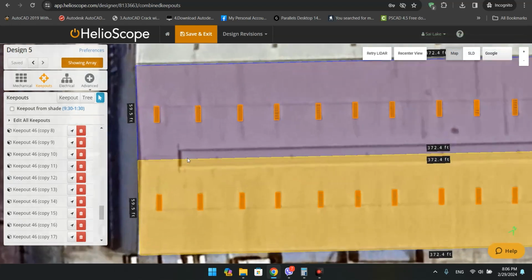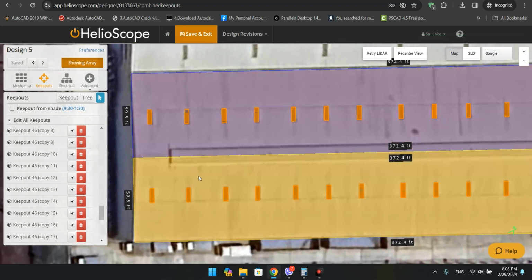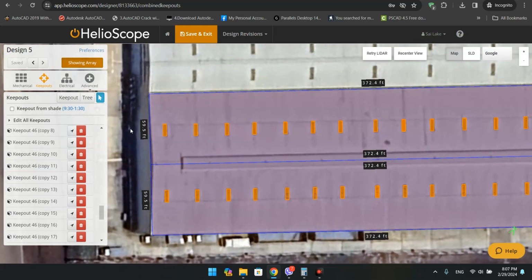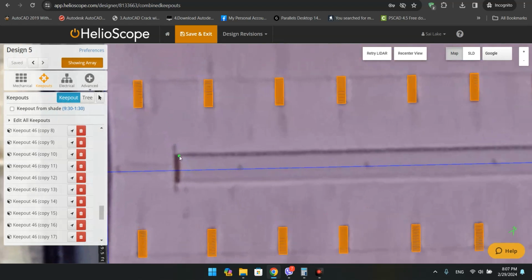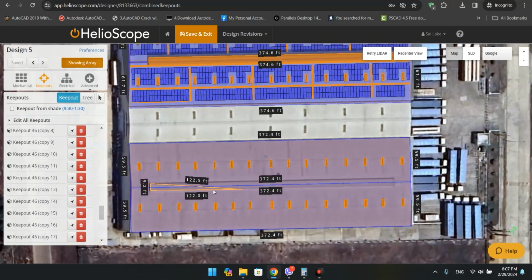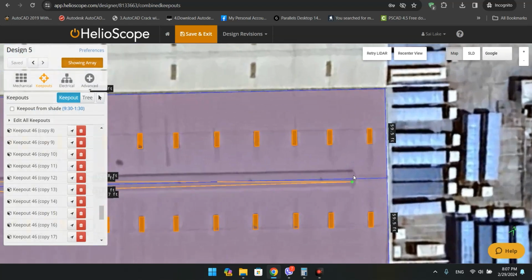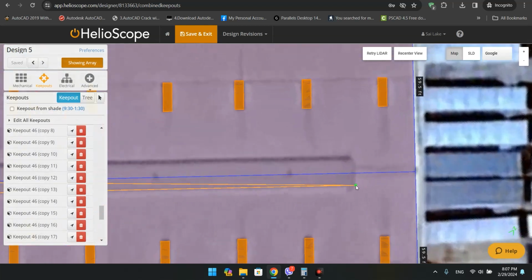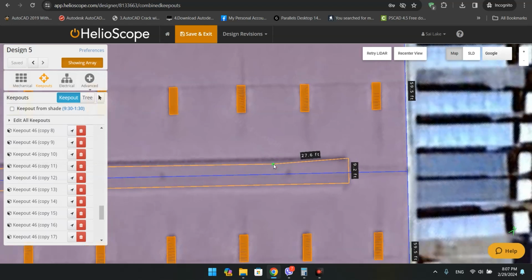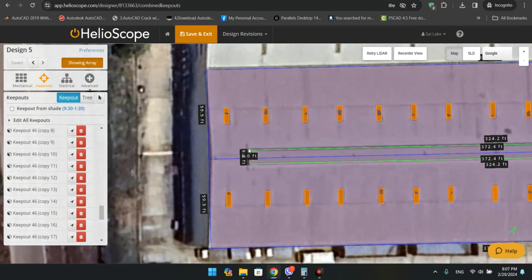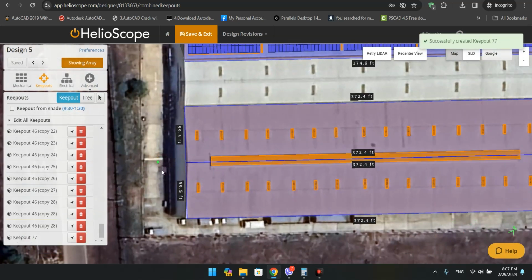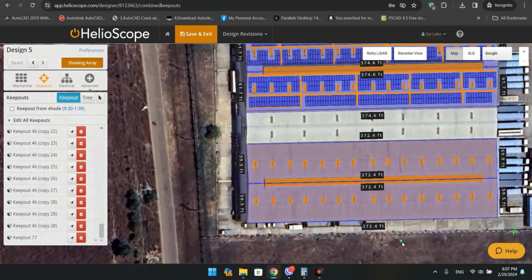So I'm going to create a ridge front here. Yeah, you might see that. I'm going to click on the keyboard tab, and then I'm going to put it on here, 9.2 feet. I'm not going to use the shift key to be perpendicular with that, because the surface itself isn't the same. So 9.2. Okay, all set.